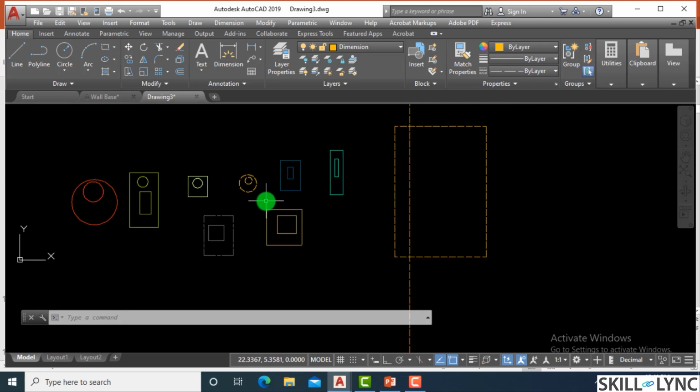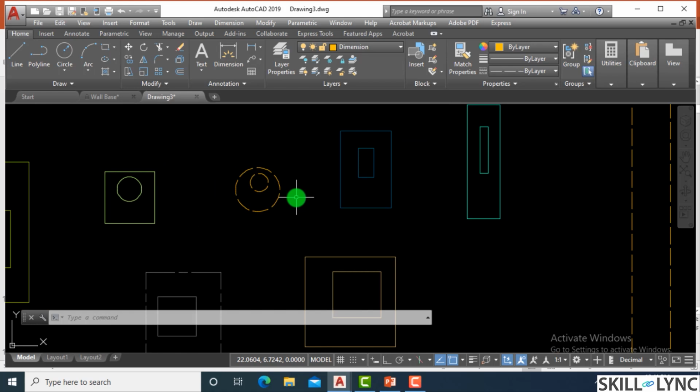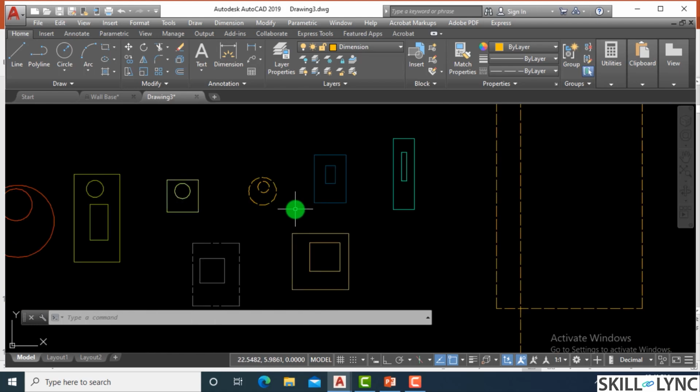The next property is the thickness or weight of the line. Line weight means the pen thickness. We use line weight in order to show the section lines and the outer lines. In drafting, line weight is a very important technique for demarcating section lines, thin lines and thick lines, and objects which are far and beyond. There are different techniques and different standards.